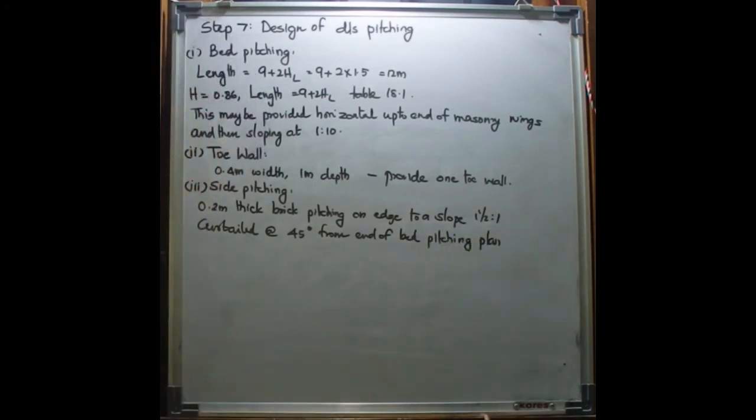Where the bed pitching in plan ends, we curtail at 45 degrees, and it is supported by a toe wall 0.4 meter thick and 1 meter depth.